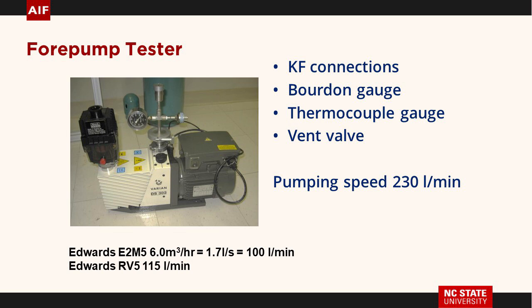So you've got a problem. My system's taking an hour to pump down. It used to take 10 minutes. What's wrong? Is it the forepump? Is it a leak? Is it something else?